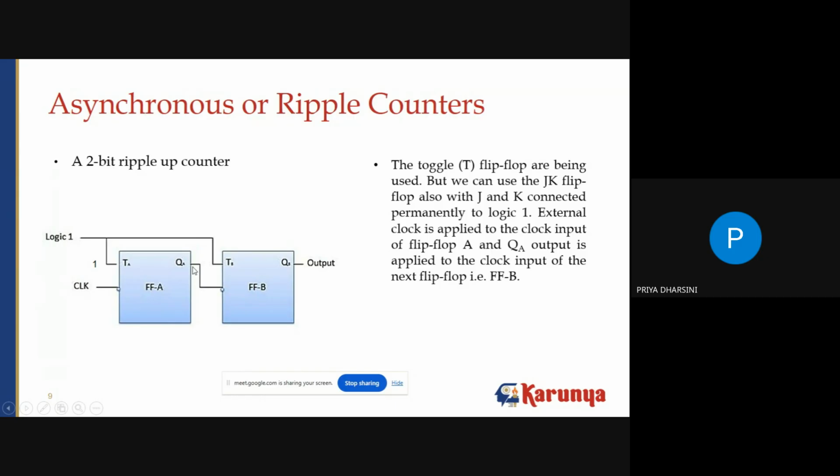Only when there is a toggling effect, when there is a shift in the data here in this particular first flip-flop. So now let's see the example. In the first case, we are initially setting it up as an up counter. It has to start counting from 0, 0, right? So we are initializing all the flip-flop outputs to 0.